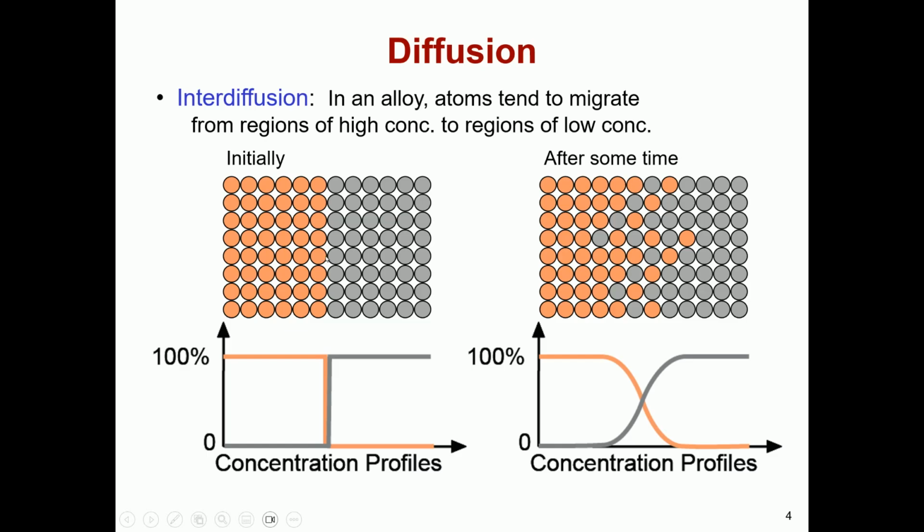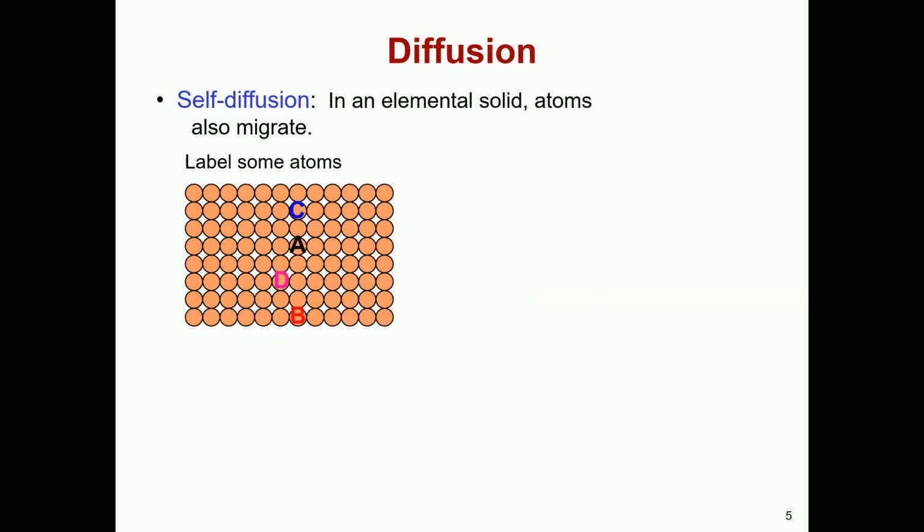For compatible elements, this intermixing happens spontaneously just by putting them in contact. However, at room temperature, it takes several decades for significant mixing to happen. In practice, this process requires elevated temperature, such as in welding. Welding also requires raising the temperature to melt the interfaces or to allow solid solution formation to occur rapidly.